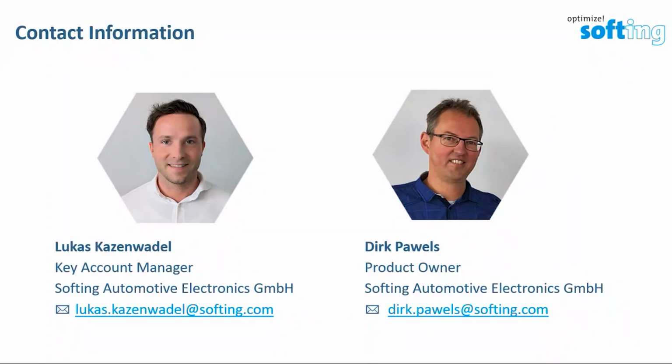All right. Next one: is the TCS test bench the tool to use to capture trace files? Not the TCS test bench, but the TCS admin can capture trace files. You can start TCS admin and start the trace, or press the write trace button, and then it records the trace. But you could also use a TCS device autark.